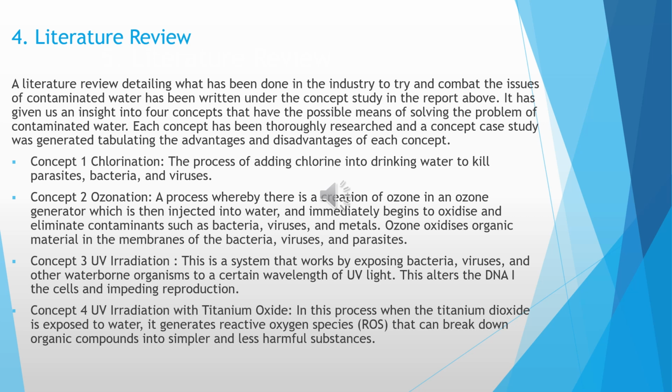Then we've got the third concept, which is the use of UV irradiation. The water in the system is exposed to UV light, which is then used to kill the bacteria and the viruses in water. And then we've got the fourth concept, which is the combination of UV radiation as well as titanium dioxide. In this process, the titanium dioxide is exposed to water, which then generates reactive oxygen species, ROS, that can break down organic compounds into simpler and less harmful substances.